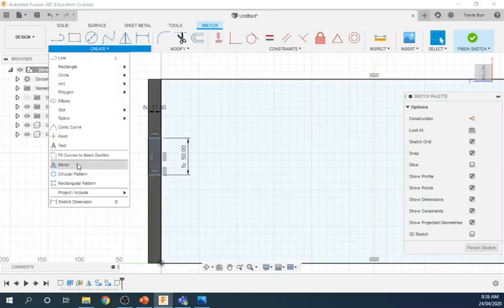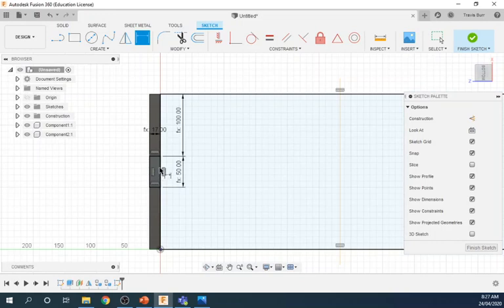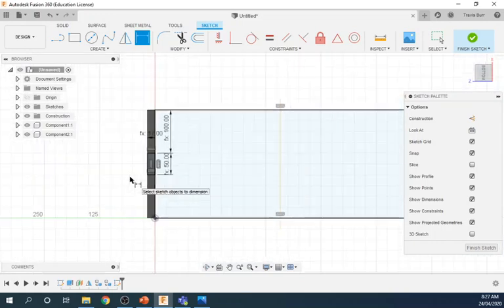So let's go create a sketch dimension, and we'll dimension this one from the edge. And let's say we can do a little more math here. So tooth width divided by 2, or sorry, let's go not divided by 2. Let's go times 2, and that's roughly centering it. I could center it out, but that should be enough for now.